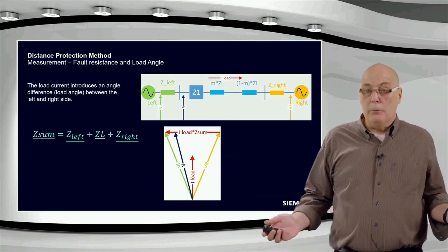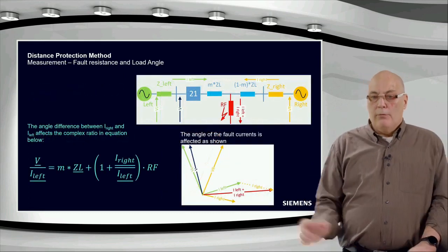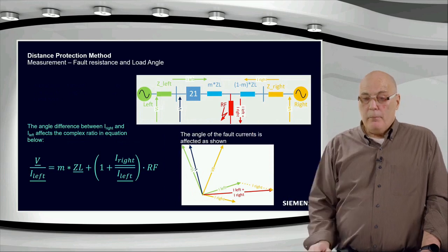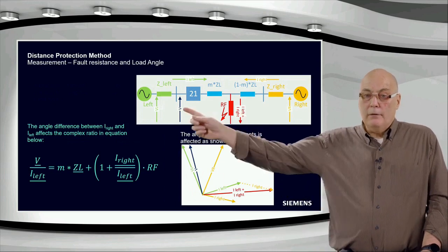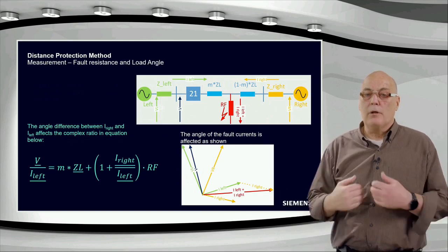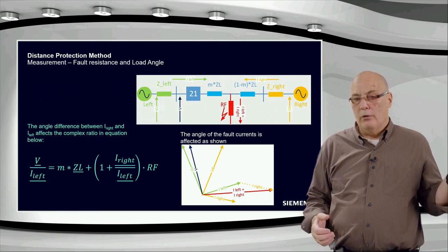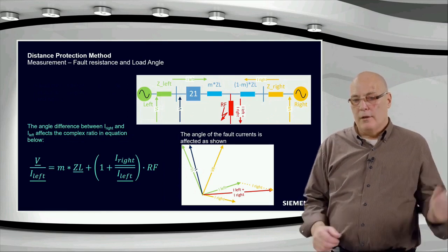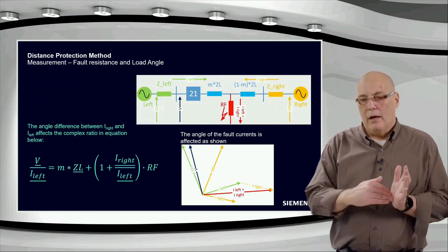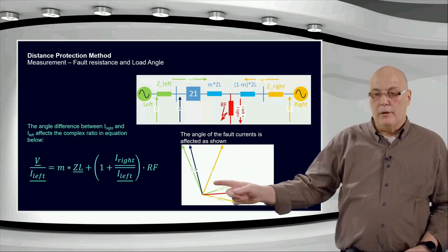because that's what typically will happen. You'll have load current, and then you'll get the fault condition. The fault condition now happening will create the current on left and right hand side to have an angle difference, because the current on the left side will come from the source on the left. Remember the voltage, the internal rotor EMF on the left hand side is the green voltage. We'll have a current, fault current about 90 degrees lagging that, which is the green current we see over here.